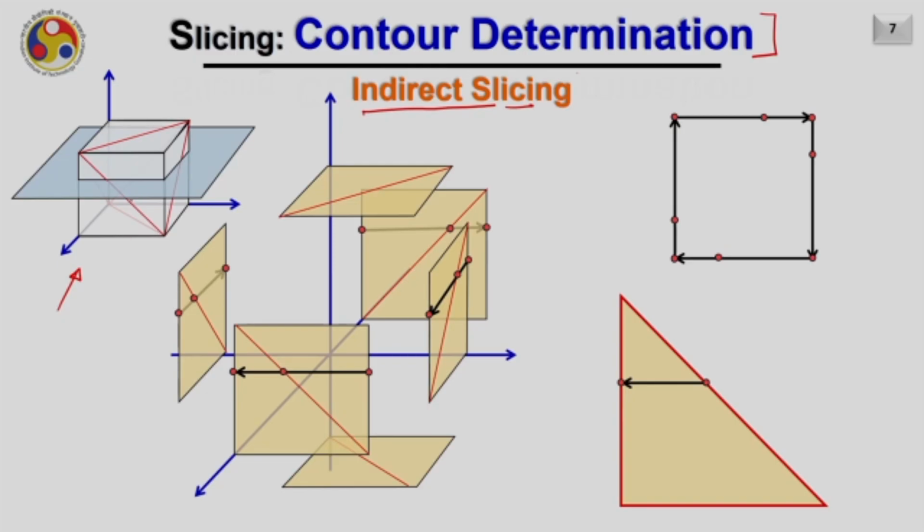For example, I am going to slice this cube at a particular height, maybe at Zi. So at Zi, I have created a plane. Now my objective is to obtain the intersection between this plane and this STL file. So if I am representing this by plane P, and this is a collection of surfaces, nothing but the solid, hence the objective is to obtain the intersection between the solid and the plane. As a result, I should get nothing but the contour.